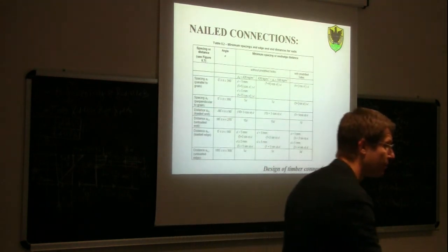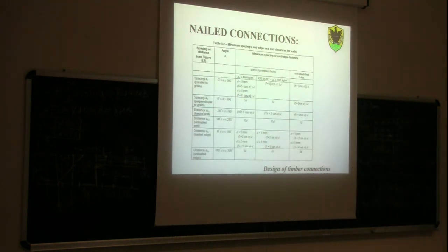Why is that? Because in a steel connection we have steel to steel, so the steel bolt and the steel plate. Here we are talking about a steel bolt in a timber member, which is much softer and much weaker compared to steel. So for this reason, in order to avoid splitting and this kind of shear failure, we have to be more stringent in terms of limitation on spacing and so on.